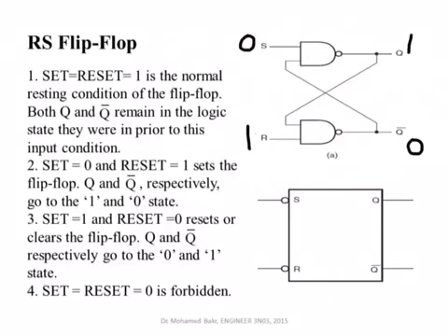Now, if you have already 1 and 0 at the output and then you make set and reset both equal to 1, this will result in no change of the output. 1 and 0 will still be kept there. Now, let's consider another case which is a reset case. So I will just erase what I have here, and then I will put the opposite condition. The opposite condition is that I have 1 for set and 0 for reset.